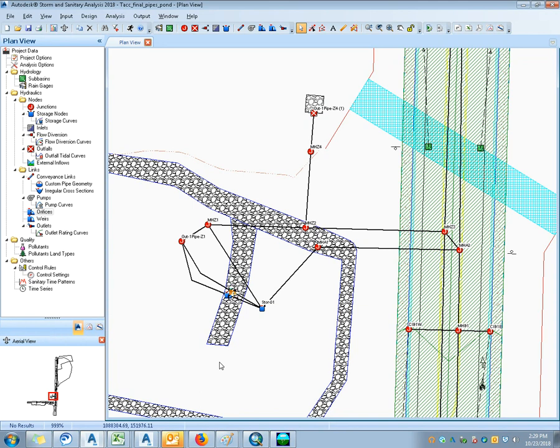Yeah, and I think the tools, even though there's some clunkiness to the importing and then restoring the model or getting it set up initially, cut out a lot of the tedious stuff that we would have to go through and then not have time to do the checking where it mattered the most. And I think we're really in pretty good shape. I think it's pretty cool to see this in SWMM as opposed to HydroCAD and doing pond nodes and a dynamic run. Totally. Yeah. I think it provides us a view of the hydraulic grade line that's much more realistic. It's pretty cool. So yeah.